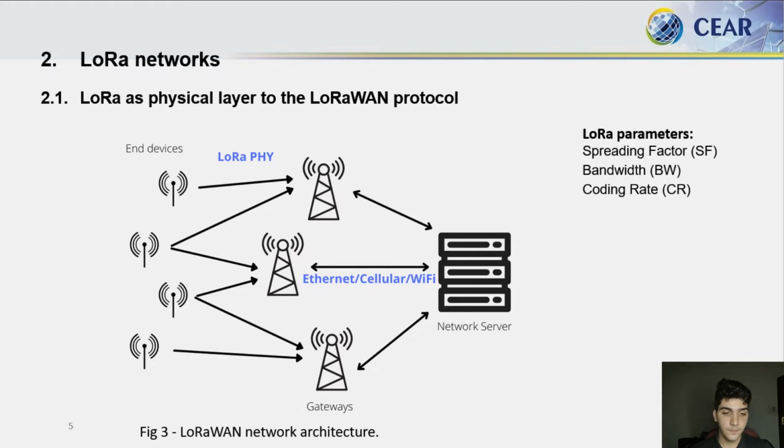The coding rate value refers to the amount of data bits used in relation to the total number of encoded bits. Another parameter that can influence the consumption of a wireless network is the package size to be transmitted. Clearly, it is possible to notice that the TOA is proportional to the package size. Thus, by changing the package size, the energy necessary to transmit data is changed as well.